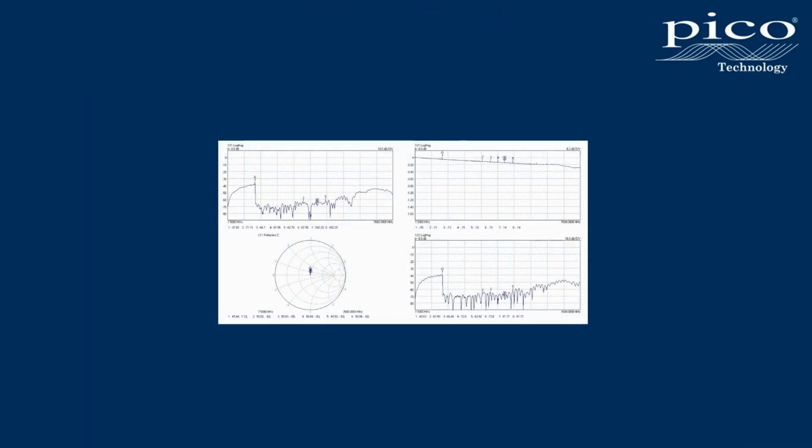As a footnote to this demonstration, I think we have seen here that TRL-TRM calibration results in bands of calibration that each have slightly different Z0. Those Z0s might be very precisely 50 ohm if we are using airline standards, but more likely, if we're using substrate-based standards, they may each be slightly offset from 50 ohm and from each other, and that might be imaginary offset or real offset.